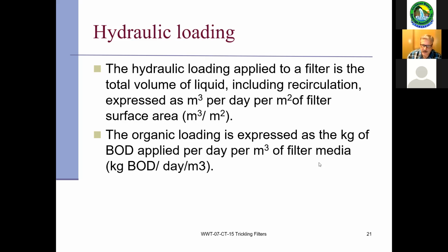Organic loading is the same as any organic loading in any other types of biological plants that you deal with. Because we're dealing with filter media and that kind of tank, it's BOD applied per day in kilograms divided by the meters cubed. So the amount applied divided by the size of the filter.